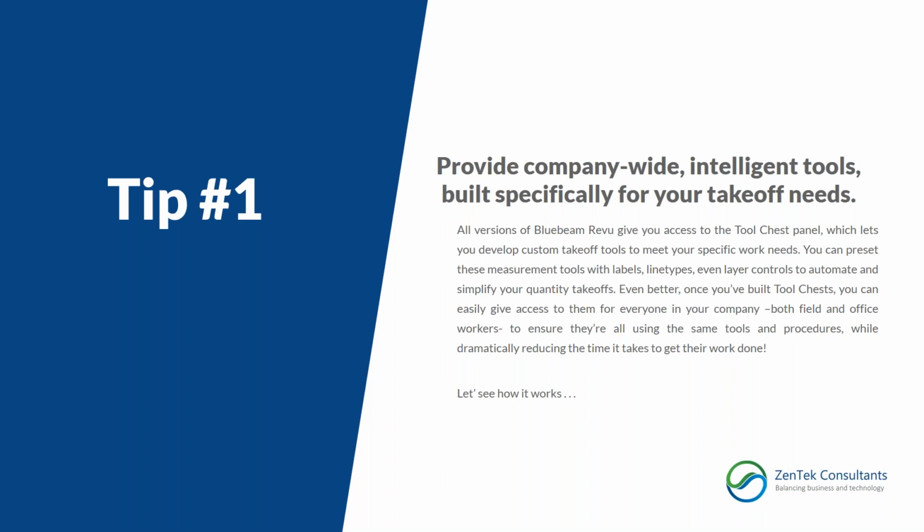But the idea behind tool chests is that you're looking to develop company-based reusable functions, right? That you've already got preset properties, display options, items, layers, all the intelligence that you need, particularly when you get into labeling and controlling quantity takeoff and estimating items. You want to be able to take that, put it into a reusable tool set, and distribute that same tool set throughout your entire company. All right, and it's a really easy process.